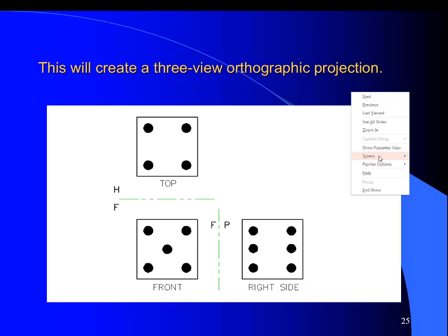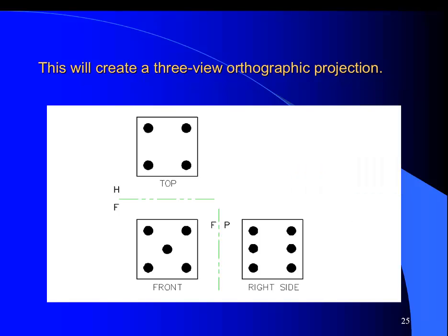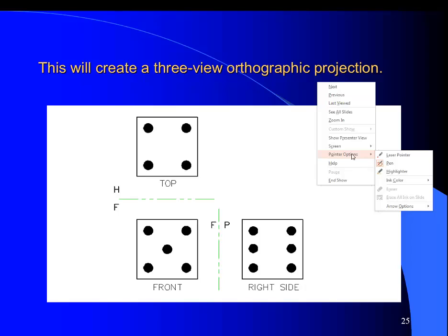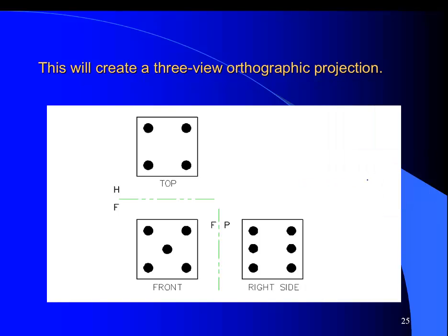Now, in technical drafting, which I know some of you have had, or some of you, if you didn't have it here, might have done it before, what we do is we use this relationship to project, and I'll do my best to draw this out. It'll probably look terrible, but typically when you have a front view, if you draw a 45-degree angle line, that was a good 45, right? Then you could project across it. So this projects over and down to the same point. This projects over and down to the same point. So that's why it's important that this space and this space are the same so that we can project around and everything makes sense.